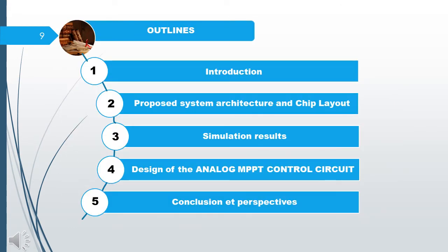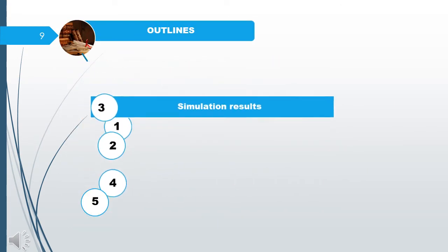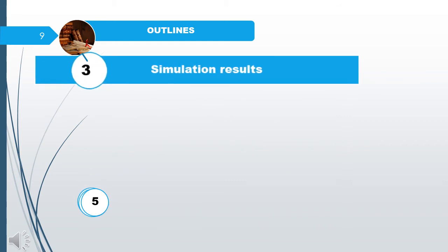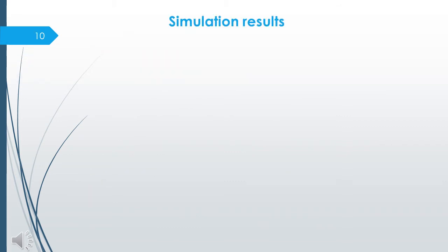We move now on to simulation results. The two-stage operational amplifier includes four major circuitries: a bias circuit, an input differential amplifier, a second gain stage, and a compensation circuit. The bias circuit is provided to establish the proper operating point for each transistor in its saturation region. The input differential amplifier block forms the input of the op-amp and provides a good portion of the overall gain to improve noise and offset performance.